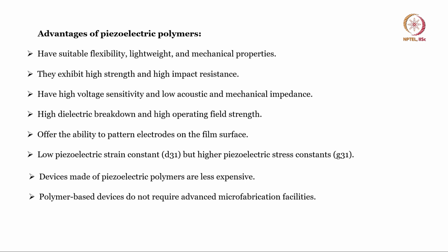So, these materials also show a low piezoelectric strain constant, but the piezoelectric stress constant of the materials will be very high, which is one major advantage of this material. Apart from that, the devices produced from these materials will be less expensive, because the piezopolymer will be fabricated in a cost effective way with very easy processing techniques.